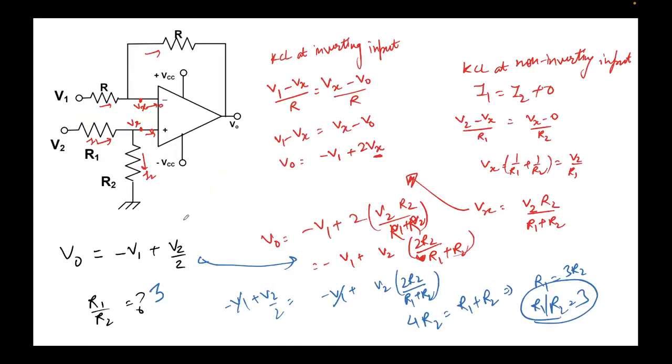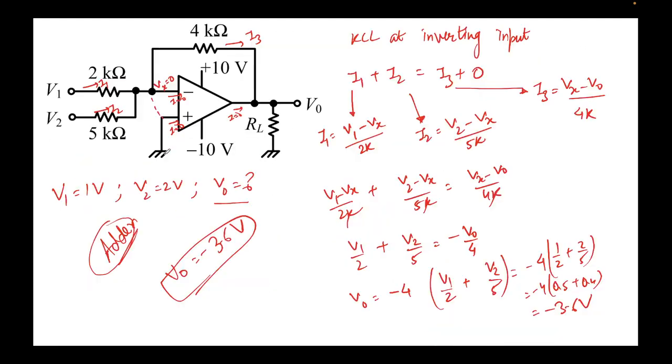In the previous question, let's look at this. I can write it as minus of (V1 minus V2) by 2. Remember that what it's doing is subtracting V1 from V2. This sometimes, not always, somebody may refer to as a subtractor circuit. Please do not go into the nomenclature. I am just saying this is a thing which you can observe. Since the two input voltages are being added, it can be called an adder circuit. And the negative sign comes because the inputs are fed to the inverting terminal and we have a negative feedback.